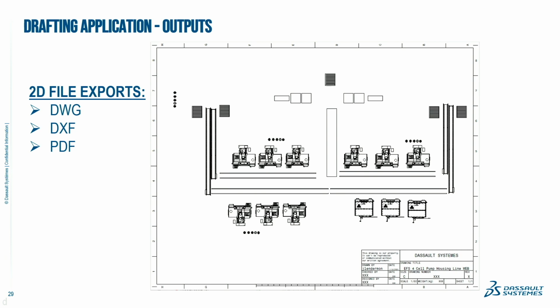Okay. Like if you look at this 2D drawing, it's basically capturing from the top view of your plant layout onto your print. So remember the original layout that I brought in had those work cells that were placeholders, and now there's machines in them. So it just recaptured everything that I brought in right then and there. So if I make any changes in the plant, I recapture it. I can move the machines around and recapture it, and it updates my drawing for me.